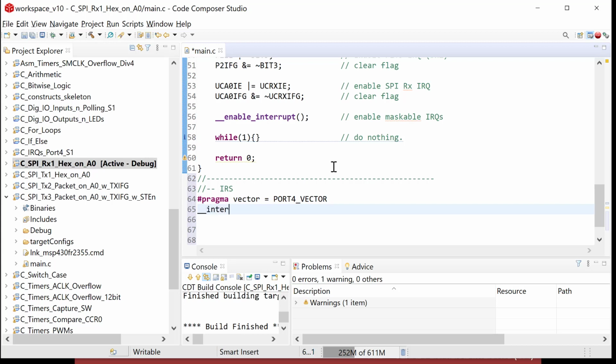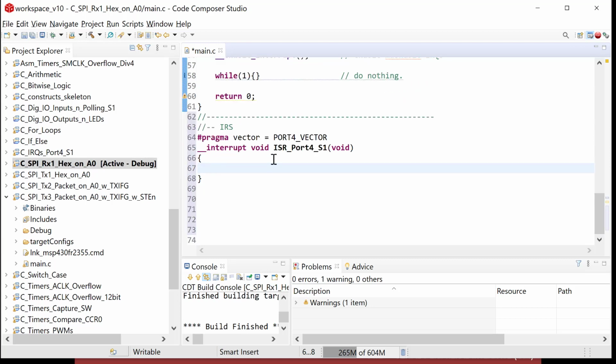By the way, this routine I'm giving you is going to be an interrupt service routine, so please return from it using a RETI instead of RET. Thank you. And of course, I'm not going to pass anything in or out of this interrupt service routine. Instead, when I get to this interrupt service routine, somebody pressed button 1. So this is ISR for switch 1.